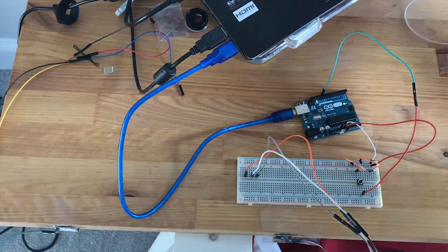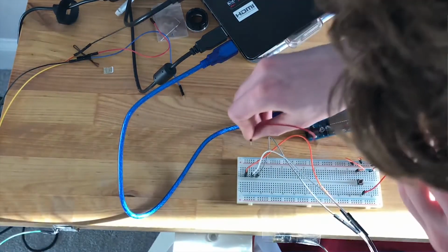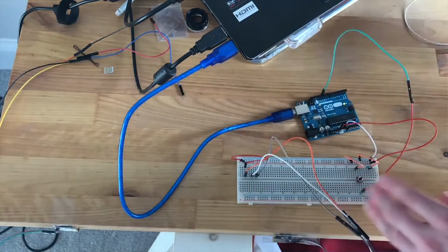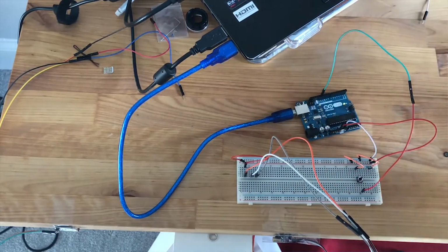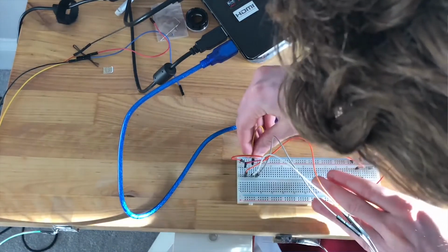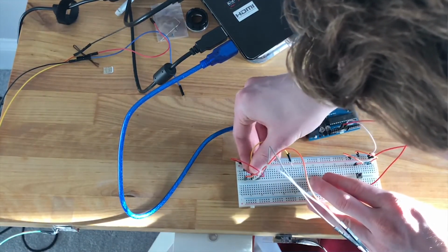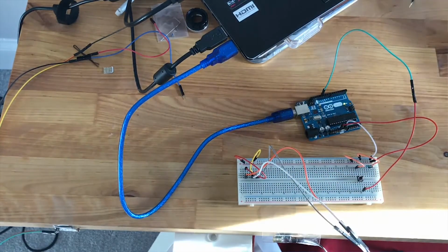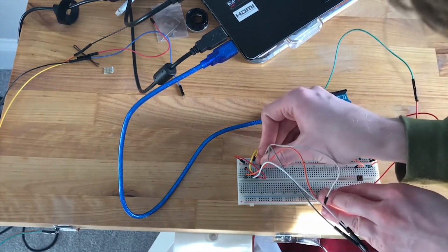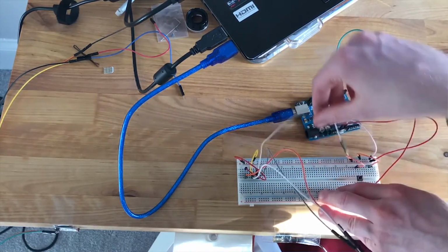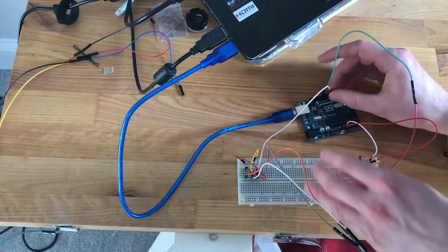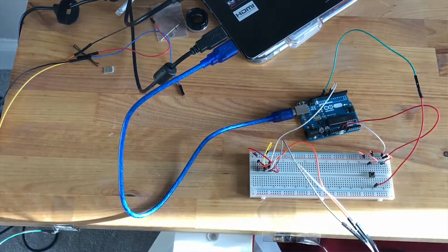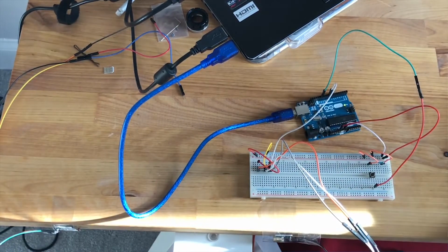So we're going to, let's connect the power up to the power channel. And then we connect the earth up to the earth, or the ground, excuse me, not the earth. And then finally, we want to take the signal to a digital pin in the Arduino board. So I'm going to go to digital 8 up there. And now let's go back to the code and have a look.